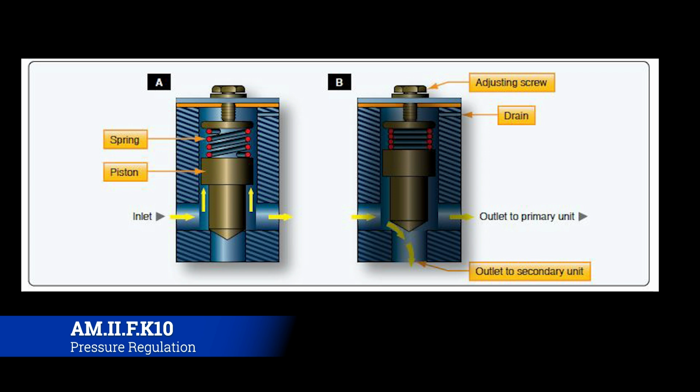So the classic example is that you want the landing gear doors to close only after the landing gear is up and locked. Once the landing gear is up and locked, then the doors can come up and close and be fine. Now, if the sequence valve wasn't there, you would eventually get an out of sequence actuation where the landing gear doors would want to close on the landing gear that's still down and locked, and you're going to end up damaging something. So a sequence valve allows you to mitigate that problem.